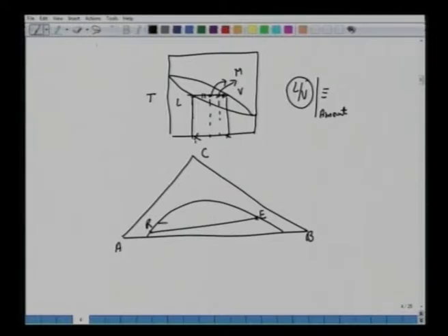Similarly, you have another tie line, with a different slope. You have all raffinate, and all extract, till you reach this plait point, at which the slope now changes. Now the extract phase composition is smaller than the raffinate phase, which means if you take these projections and plot just like Y versus X.